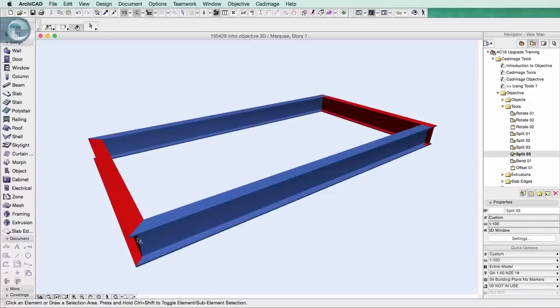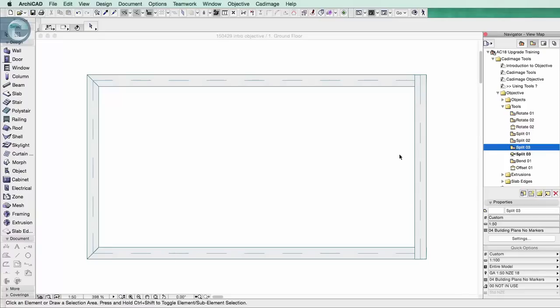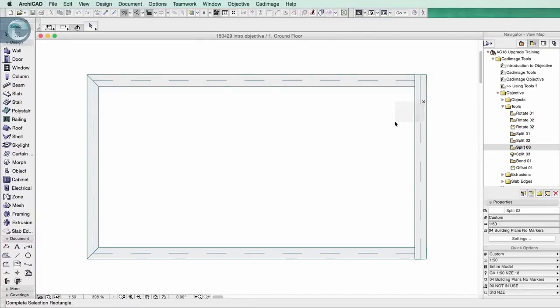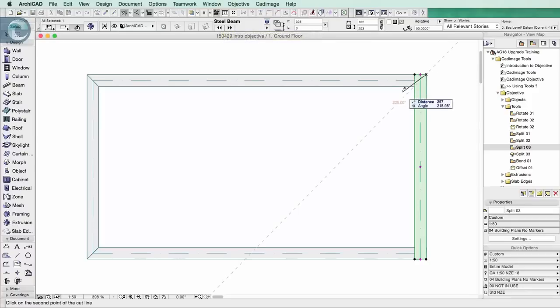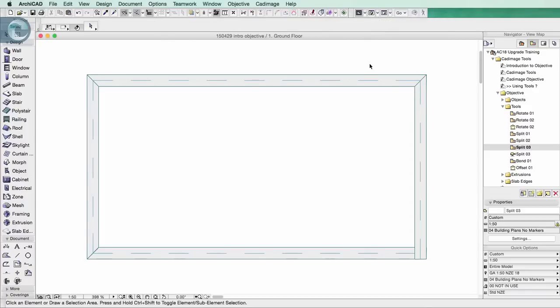And you'll see what I've done is I've corrected these corners. I've added the splits so that this now connects properly, but I haven't yet done the other side. So if I go back, it's a case simply of pick up the component, and I am going to split there at 45 degrees, keep that side selected and then delete it.